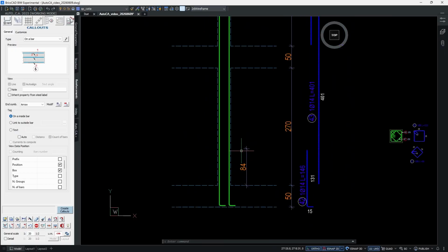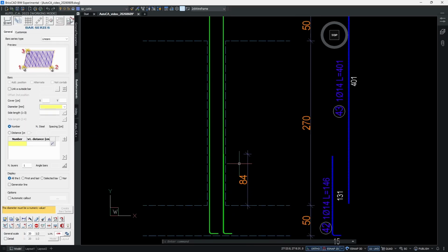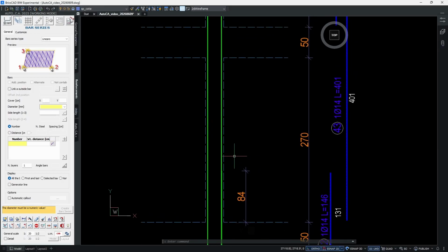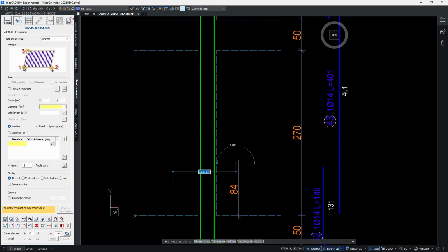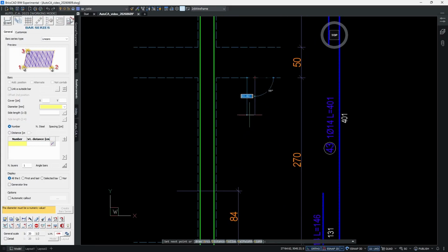Now, I'm going to create the 3-zone stirrup distribution. And I'm going to select the segments directly from the drawing. So we need to define all 3 segments here. The first segment is going to be along the overlap, and the other segment is going to be counted from the bottom of the beam where we need to arrive with our distribution.